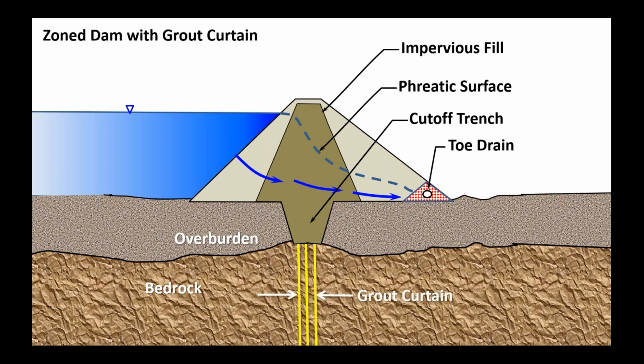And then to prevent the seepage through the foundation, we began to drill and inject a grout into the foundation to seal up all the cracks and prevent seepage through the foundation. So now we're finding ways to control seepage through the dam.